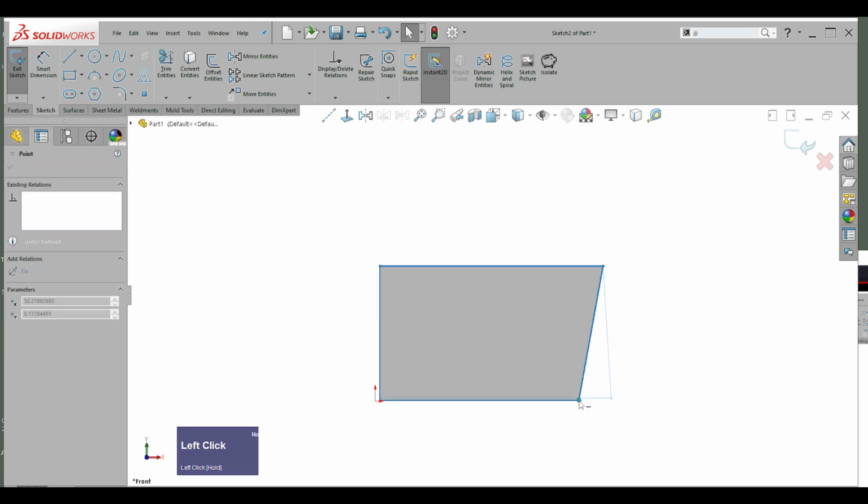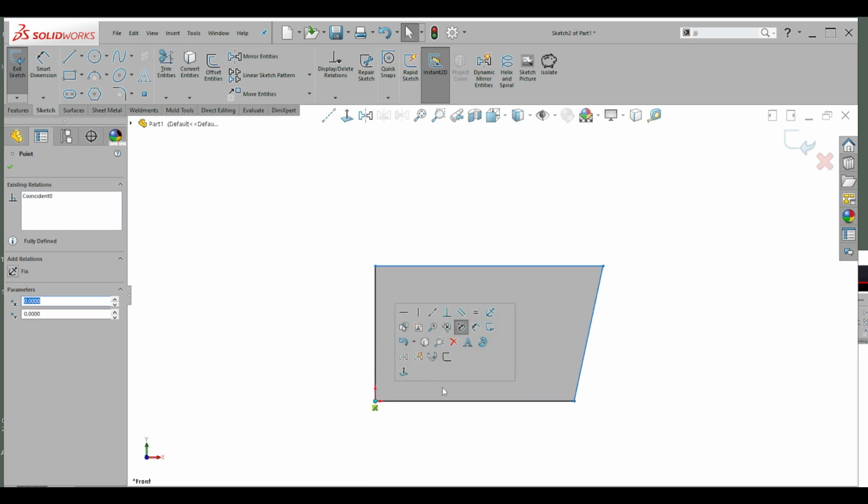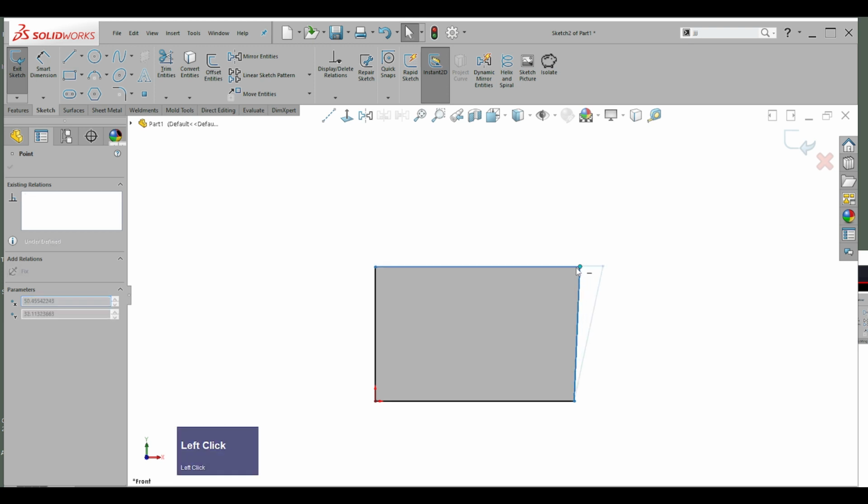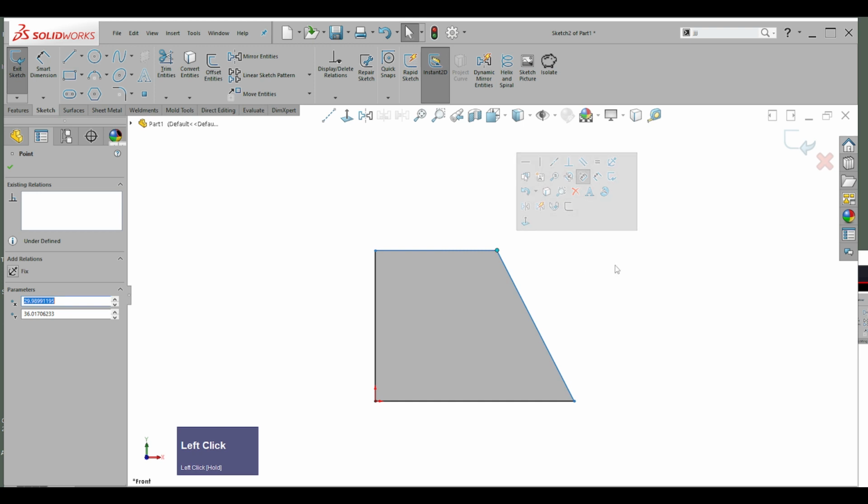All right, I can drag a point to the origin point. You'll see this little crossed thing that's called coincident. It's a coincident constraint. The moment I do that, the lines go black, meaning they are constrained, they are properly defined. Okay, so I might use the word defined and constrained interchangeably.